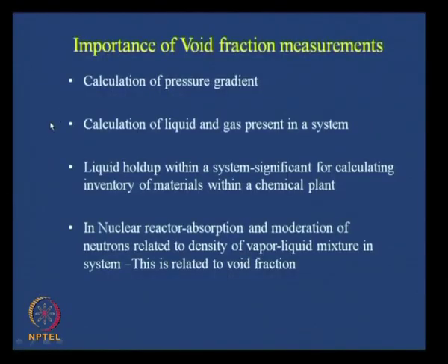Now, what is the importance of void fraction measurements? As I have said, the void fraction gives us a measure of the in situ composition of the two phases. Therefore, unless we can measure the void fraction, we do not know the composition. Unless we know the composition, we do not know the mixture density, the in situ velocity, etc. So the first thing in industrial situations is to calculate the pressure gradient or the pressure drop.